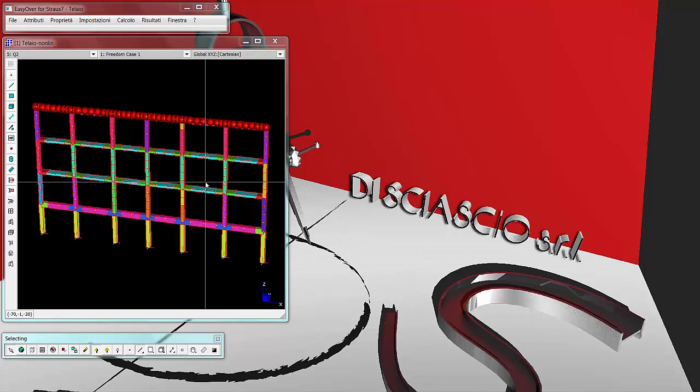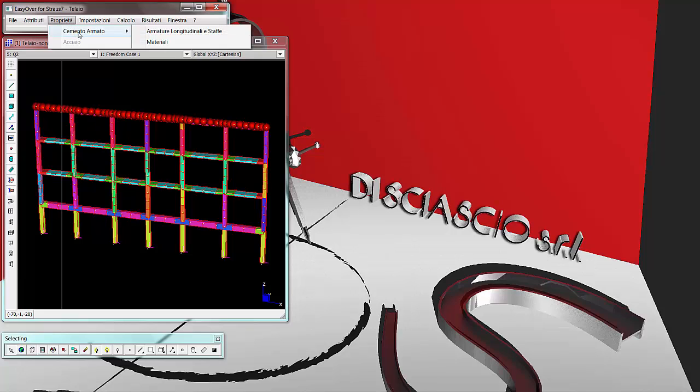Next, we will analyze the functionality of the application, for simplicity making reference to an example of a plane frame, though the program can be applied to any model, even a three-dimensional one. In the Properties Reinforced Concrete menu, you can define reinforcement properties and materials that, in analogy to what is done in Strand 7, can then be applied to the beam elements.